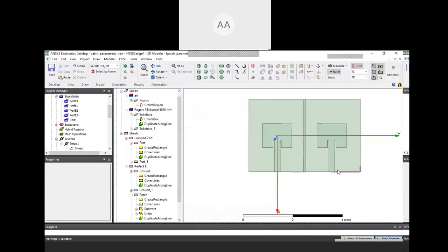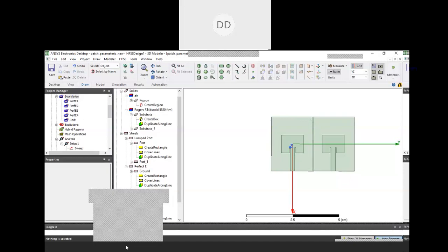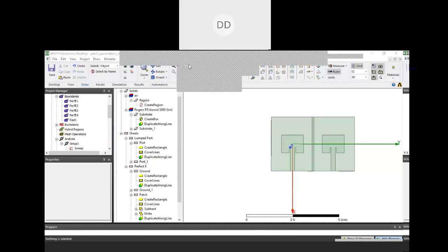If you are drawing this kind of structure, where everything is united, in that case you have to take a bigger radiation boundary, with radiation boundary on all sides. But if you are going for the domain decomposition method, which we will discuss on the final day, in that case you will have a periodic master slave boundary here, and that can be repeated n times. It will become clear on the fifth day. So I request the participants, for this MIMO question, to please wait for the last day. After that, if you have any query, you can post it again.